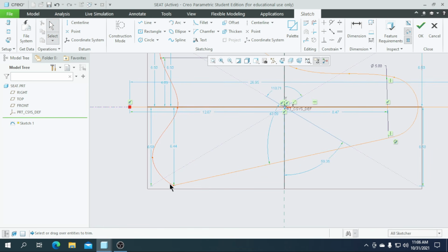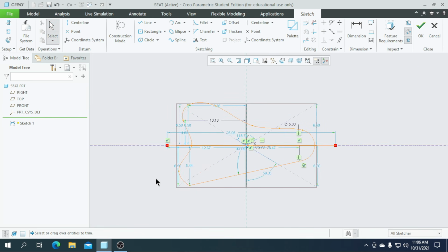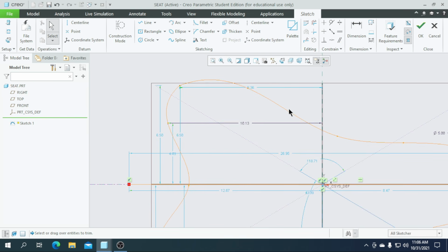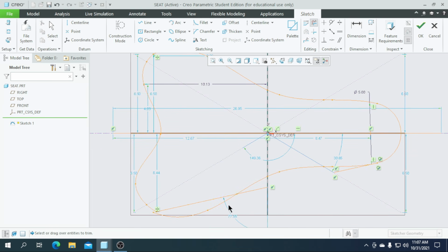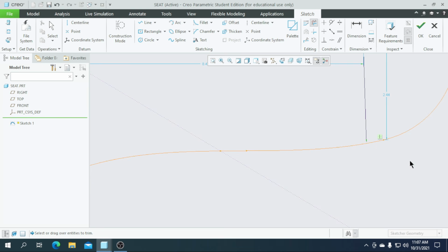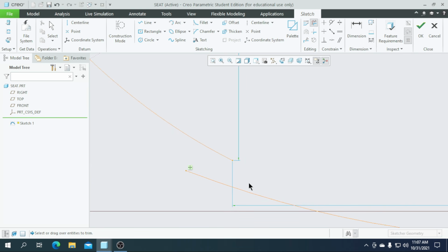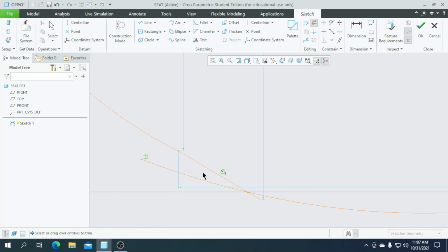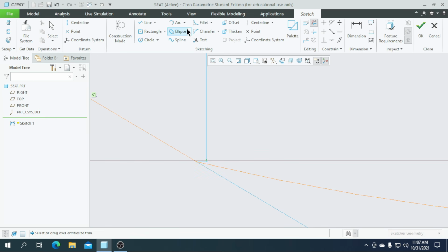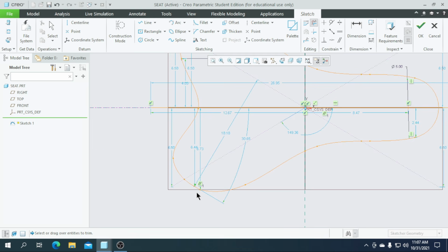Then select the entire single tab. Before that, select this curve, and I am going to mirror this towards this center line. Then delete the unwanted segments. So we have to make this as a coincident, or better you can draw a line to coincident these two planes, and delete the unwanted segments. And here I finished a seed part.